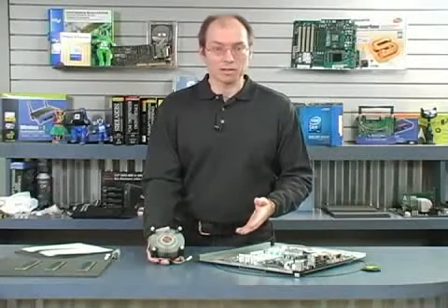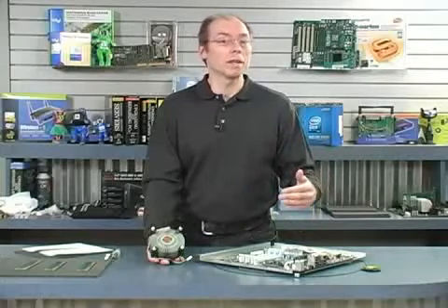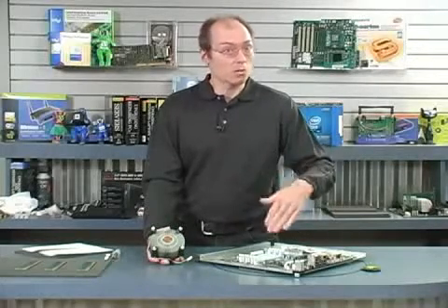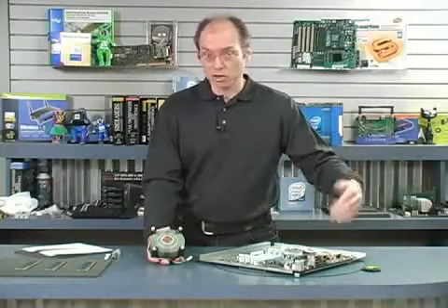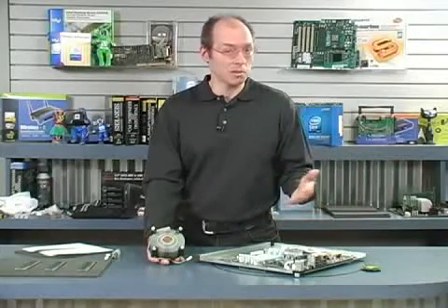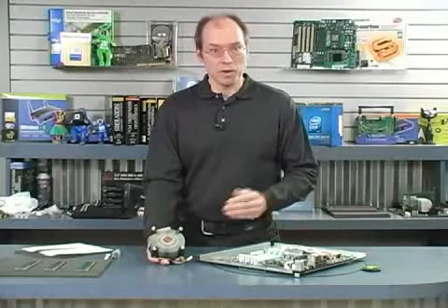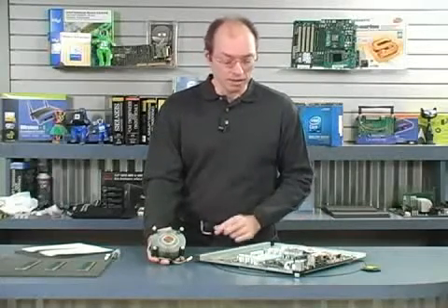And what that'll cause is that in many cases the processor will overheat or not be able to run at its full speed, because modern processors don't actually overheat to the point of destruction or stopping. What they'll do is throttle themselves down. So you'll end up with a system that for some reason doesn't seem to be running as fast as it should be. The real reason is, you don't have a good bond between the heatsink and the top of the processor.